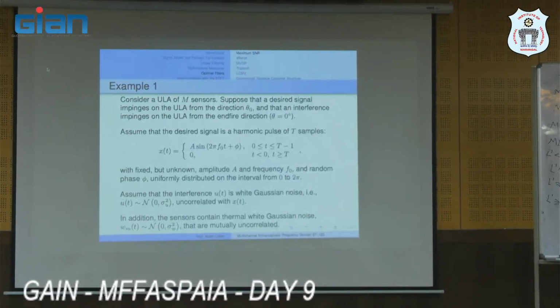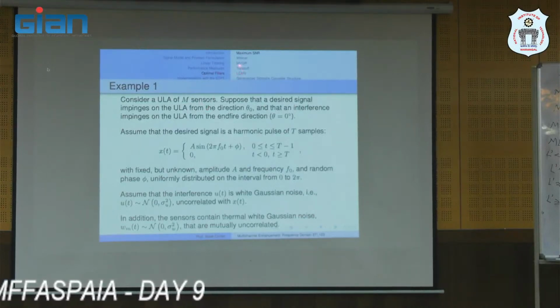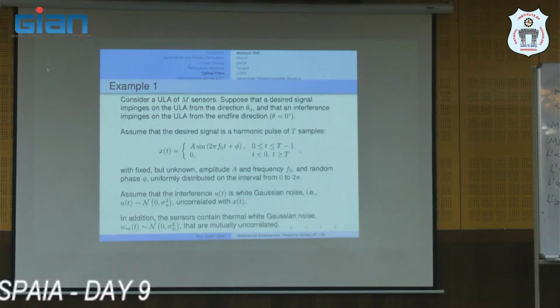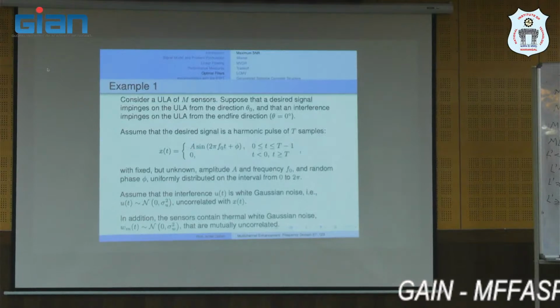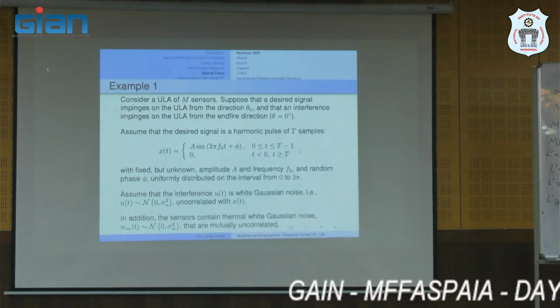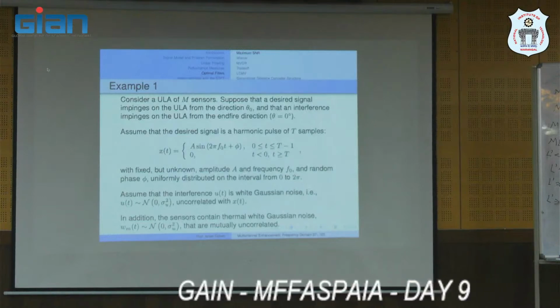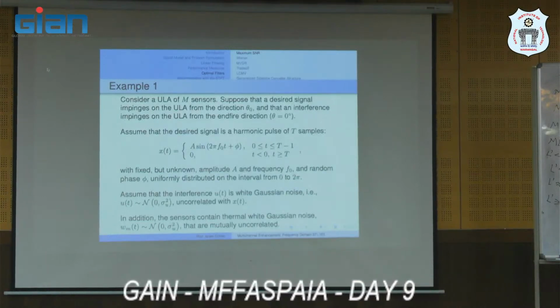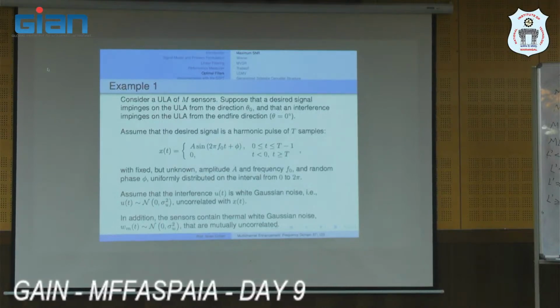So obviously, because we add constraints, the output SNR will be lower than the MVDR, but at least we're able to eliminate weak noise sources, which are very significant, not in terms of the power, but by other type, or maybe according to their characteristics or something else. So we still want to cancel them, okay?